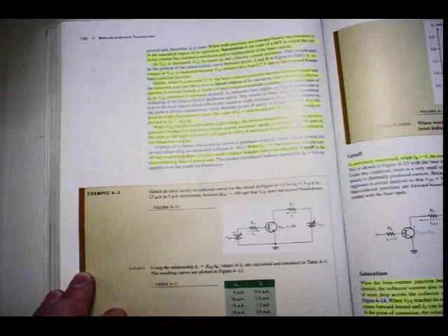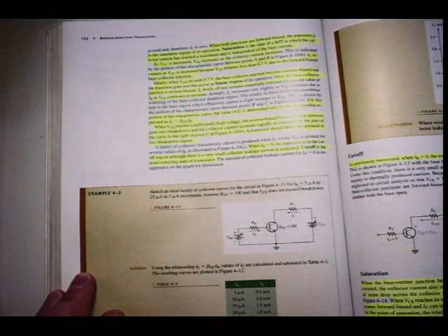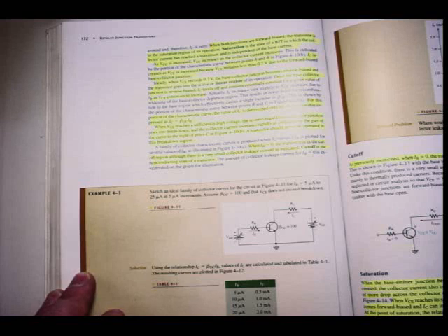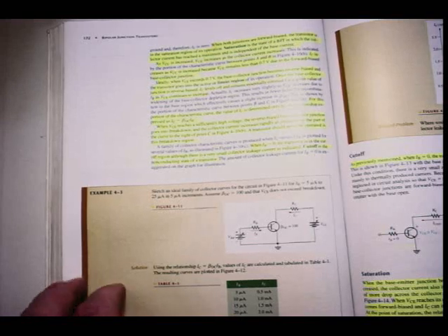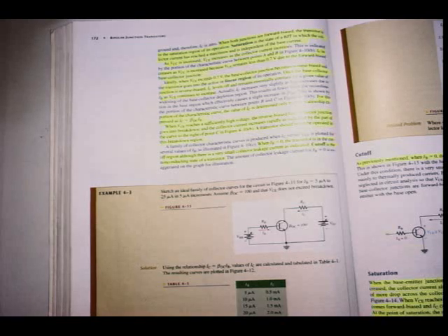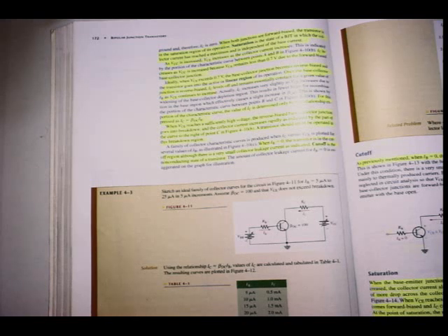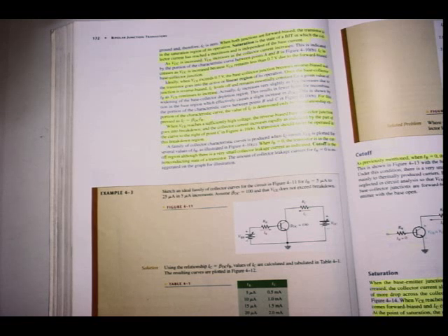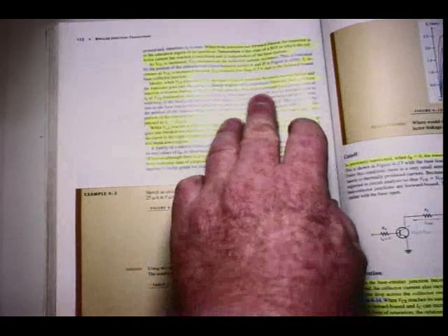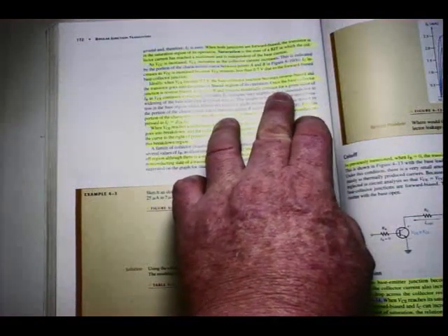Ideally, when VCE exceeds 0.7 volt, the base collector junction becomes reverse biased and the transistor goes into the active or the linear region of its operation. Linear region of operation means that is the area where I'm going to use the transistor for amplification. When IB is equal to 0, in other words the transistor is off, or it goes into maximum current, it's in saturation. Those are the two areas where I will use it as a switch. So it's either in cutoff or saturation, the switch is off or the switch is on, or in the area in between I will use it for amplification, which is called the linear region, but we will discuss that in much detail as we go along.